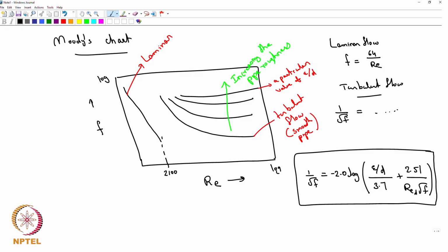But whenever you are going to do a design problem, you do not want to stick to exact numbers. Whatever number you get, you want to give some cushion to it. You'll take 15% or 20% extra, whatever is required. So there things get adjusted. You could either use the equation or the graph. The graph is definitely going to be better. So let's move on.